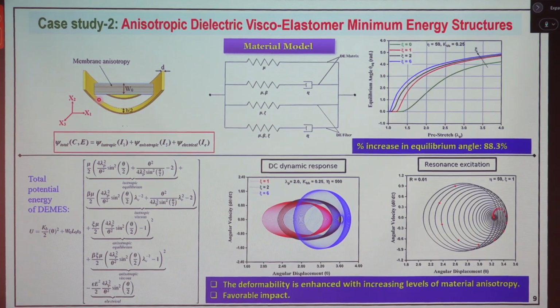So the mathematics is very important. Now you do not have a simple rheological model. You will have a model in which two Zener models, one for the matrix and one for the fiber, are taken into account. You can see clearly that this is transversely isotropic. We are incorporating the fiber in this direction. In the transverse direction, the properties are isotropic, they are the same. Only in this one particular direction is the property going to vary, because we are considering the transversely isotropic case.